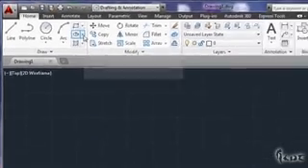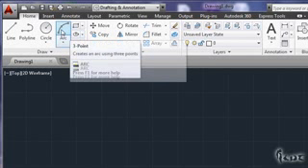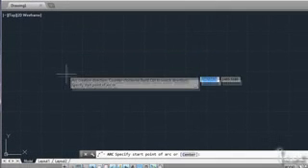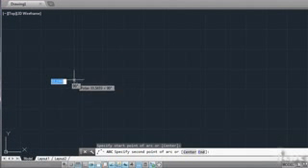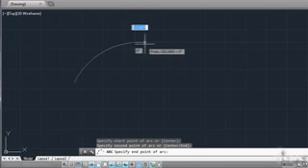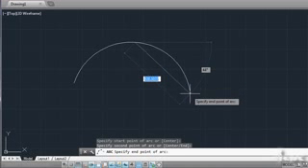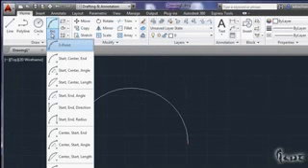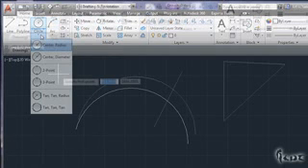Let's for example draw an arc. Click on the arc button. If you read the help information, you need 3 points. Each point is set every time you click on the workspace in the position decided with the pointer. When all 3 points are done, the arc will be shown. Other shapes will need more or fewer points, or even distances or angles. These 3 will let you draw anything. You can choose the order to set points or distances or angles by clicking on the black arrows above and selecting the way of drawing, as explained before.